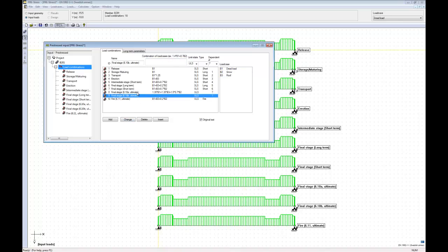If we take a look at the 610B, I will have another way to enter the values: 1.35 times 0.89, which is also a parameter specific to Sweden. Normal Eurocode has this to 0.85, and I will have the dead load and the roof, and I will have 1.5 times the snow load in this case.